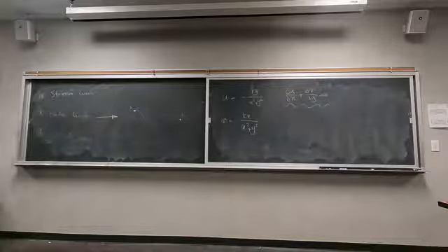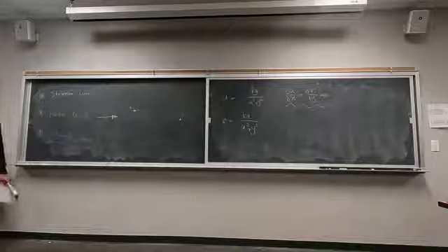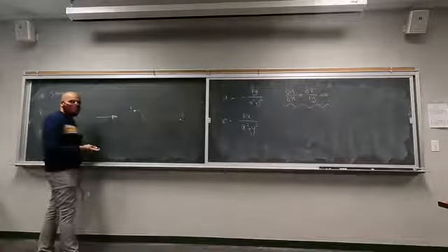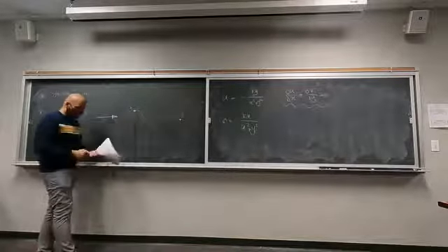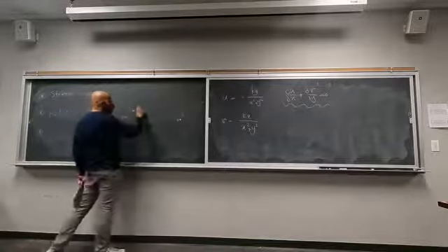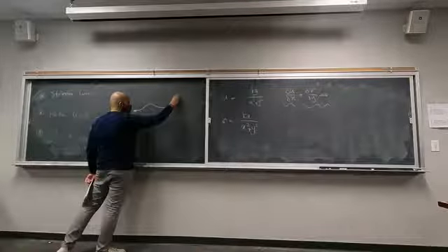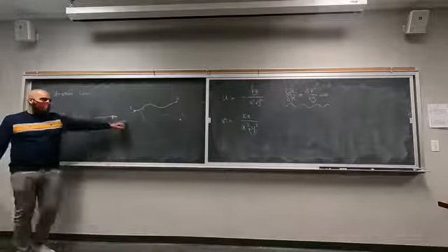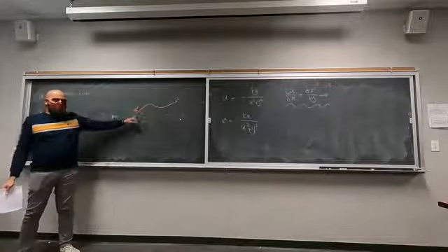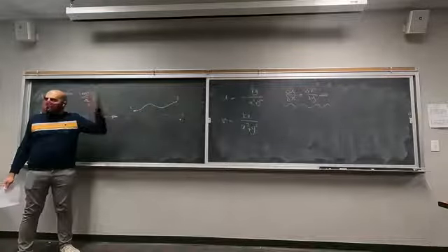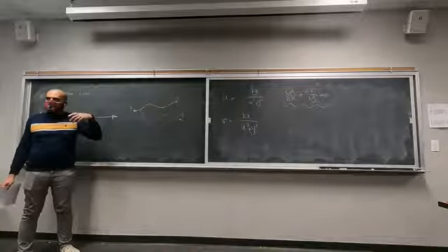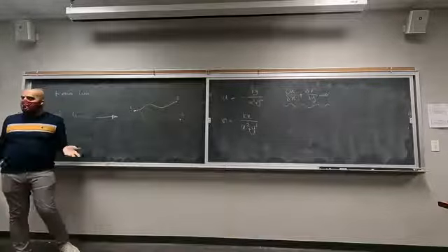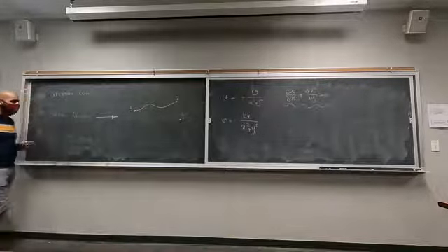If we are dealing with unsteady flow, the path line for two different particles that are passing through the same point at two different times is going to be different because the flow is unsteady. So the forces that are going to be applied at this location are going to change over time, or partial rho partial t, partial whatever partial t is not 0. Does this make sense? Path line.